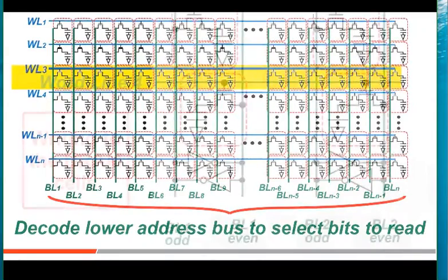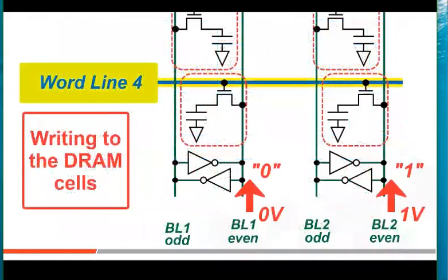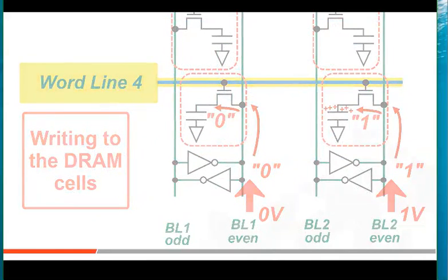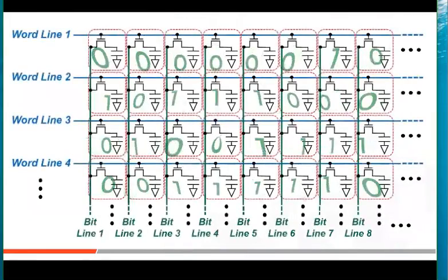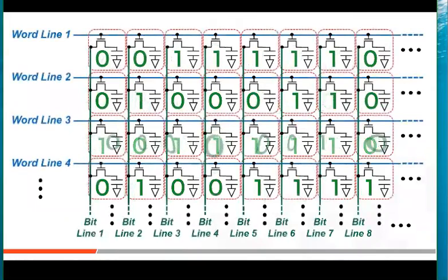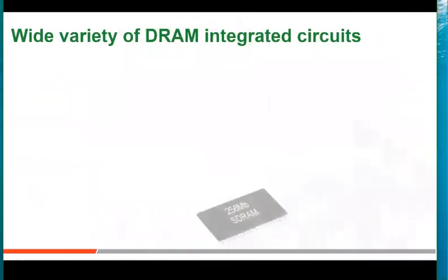Now, let's look at the write instructions. For a write instruction, the targeted bit lines are driven high or low depending on whether you are writing ones or zeros, and the capacitors inside the selected memory cells are moved to those written values. In DRAM memory, these bits can be read over and over or written over and over infinitely without damage to the structure and without losing content. That is different than flash, which has a destructive write and erase operation.